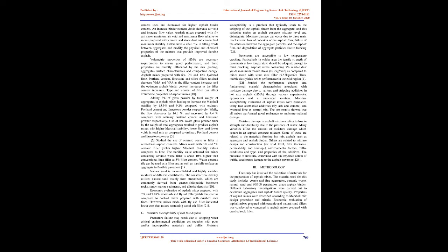A portion of the mineral filler that is finer than the asphalt film thickness mixed with asphalt binder forms a mortar or mastic and contributes to improved stiffening of the mix. The filler forms filler asphalt mastic, which has binder consistency characteristics that improve the bond between asphalt cement and aggregate. The other portion of filler larger than the asphalt film thickness behaves as a mineral aggregate and serves to fill the voids between coarser aggregate particles, thereby increasing the density, stability, and toughness of the compacted mix. 5, 11 and 12.